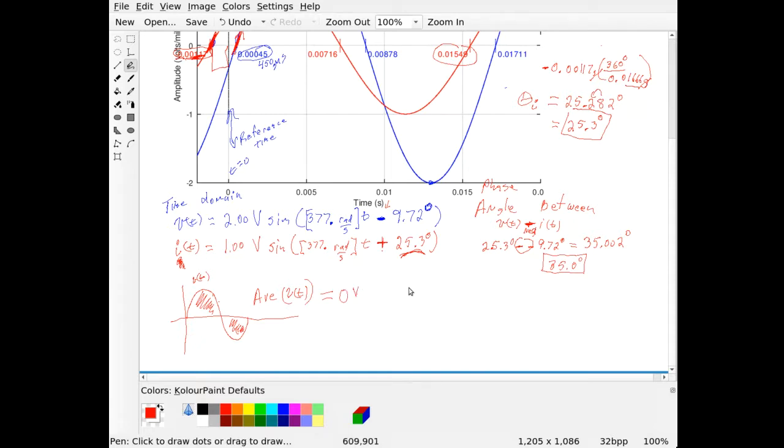And we know from DC circuits, at least, that power is equal to volts times the current in DC. So if we were to take the average voltage of our AC waveform and plug that in for the voltage, that would indicate that we have a power of 0 watts, whatever the current is.